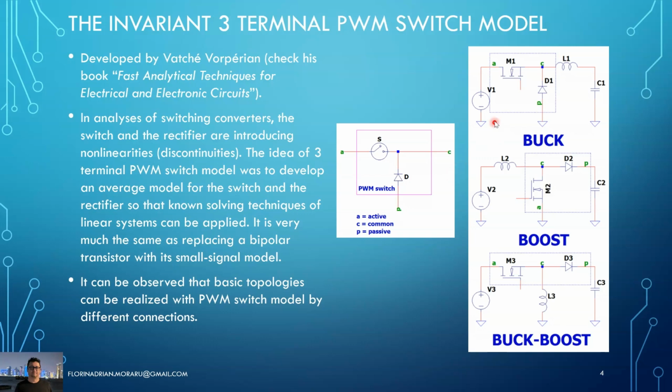We will see later on how this can be used. This three-terminal PWM switch model is called invariant because the equations involved here are not changing regardless of the topology it is used in. So it is therefore a very convenient tool when it comes to analysis of switching regulators.